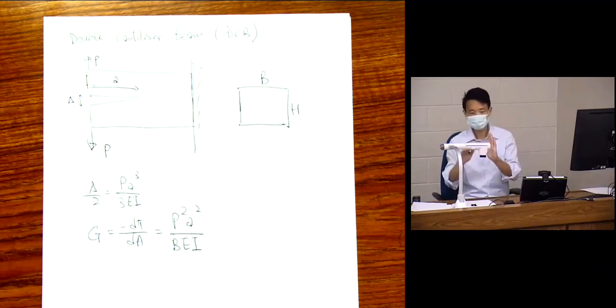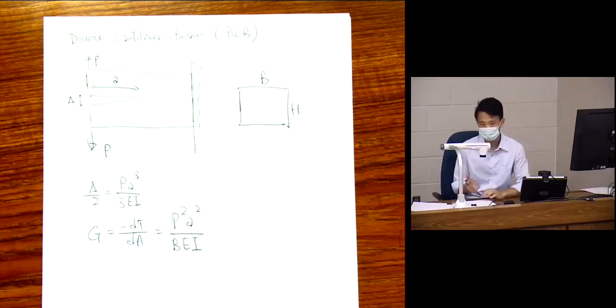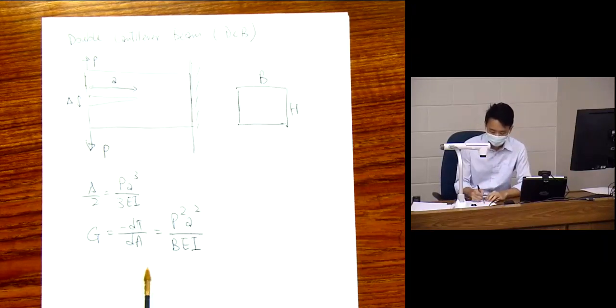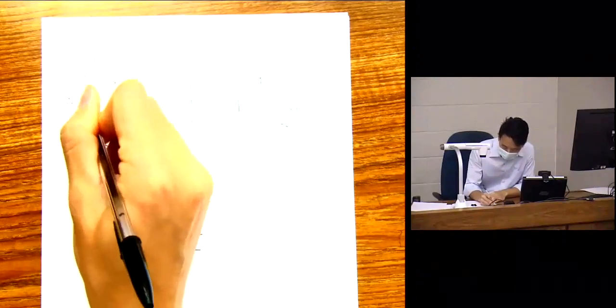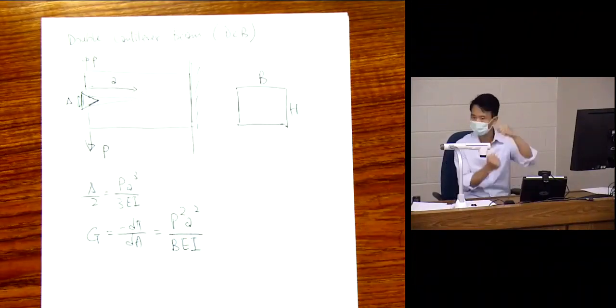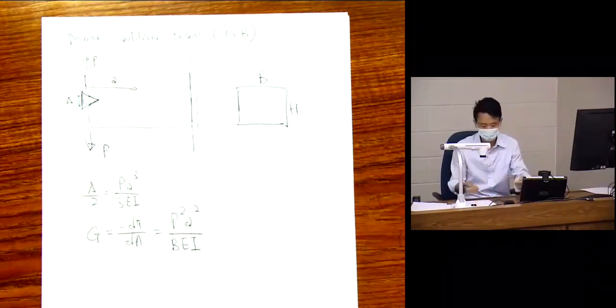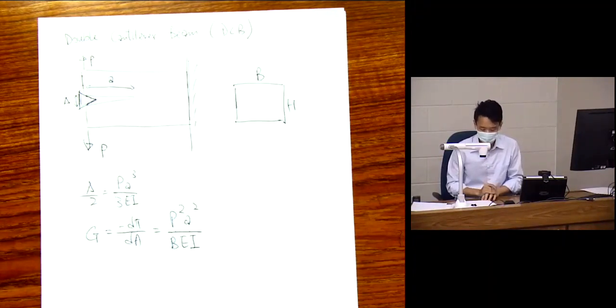So whenever the crack goes a little bit more, you get even more energy release rate available to advance the crack. So it's not so good. So this is G if you load the cantilever beam by a force. All right, so there's another way of loading the cantilever beam, which is to put in a wedge. Instead of pulling with two forces, you have a grip, I can hang a weight on these two points, then I can control the force P, and that is how I load the specimen. It's a load control experiment.